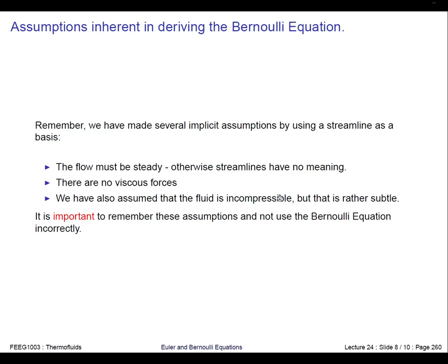We've also assumed that the fluid is incompressible, and this is an assumption that we're making in part one. It's not generally, doesn't have to be true, but in part one this is very much an assumption. Okay, so when you apply the Bernoulli equation, you've really got to make sure that these things are all true, and if you can make sure that that's the case, then you can apply the Bernoulli equation, you can work out the pressure distribution in the fluid, which is very handy.